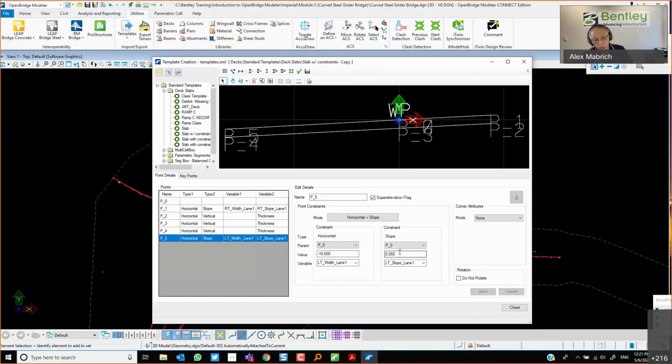So, but then because roadway hasn't given me yet the actual super elevation file. If I have it, I can go and assign it, and then the software will just rotate the deck automatically, right? If you want to do that, you can use exactly the same template that we have. Just make sure that if you're going to attach the super elevation, in order for the software to understand that reaction, these have to be on, like it is, super elevation flag.